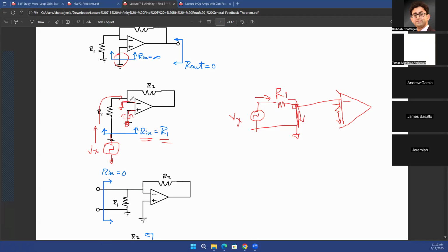What is more interesting is that you also had this R2 resistance connected to the same terminal. So you actually had R2 connected here, connected back to the output of the op-amp, which means that it is getting connected to a ground. So there is the resistance R2 as well. But current does not go to this path. Why? Because it already sees an AC ground here. The current can go to the AC ground directly. Current does not need to take the path of more resistance. It will always take the path of least resistance.